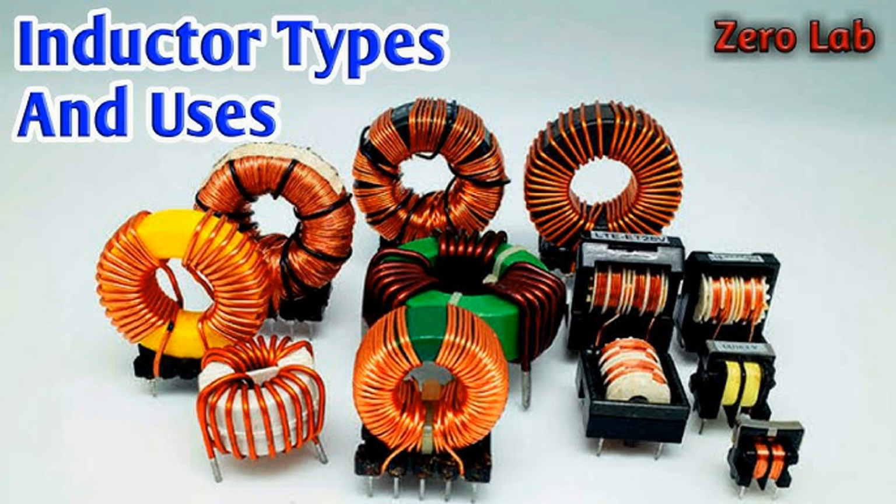Power supply filtering. Application: chokes are used in power supply circuits to block high-frequency noise generated by switching power supplies and other high-frequency devices, ensuring a clean DC output. Example: in a switching power supply, a choke inductor is placed after the rectification stage to block high-frequency ripple from the output voltage.